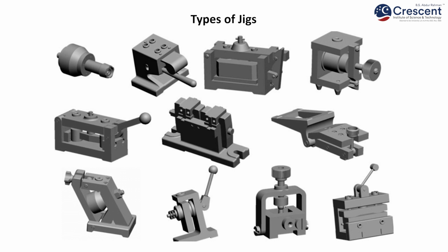Boring jigs. So what is a boring operation? We enlarge the already existing hole. So boring jigs guide boring tools for enlarging or finishing the pre-existing holes accurately. Punching jigs, punching operation is carried out.